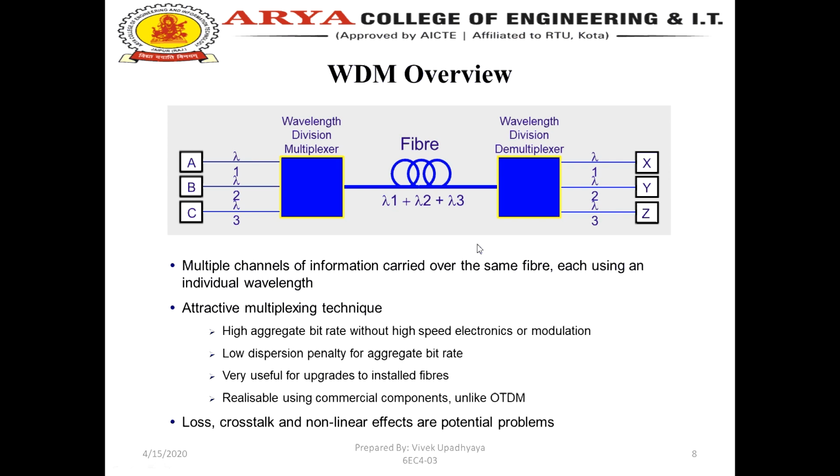It is an attractive multiplexing technique. The reasons are: it gives a high aggregate bitrate without high-speed electronics or modulation, it has a low dispersion penalty for aggregate bitrate, and it is very useful for upgrades to installed fibers.